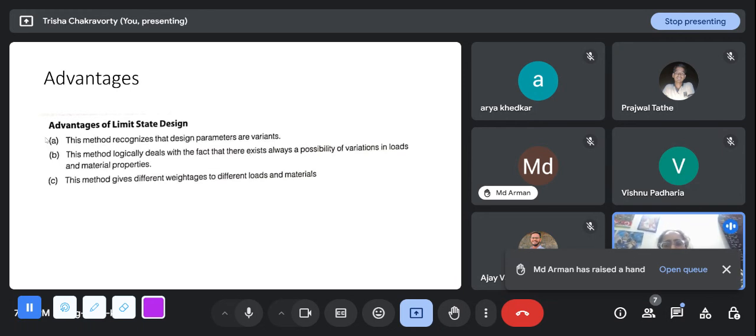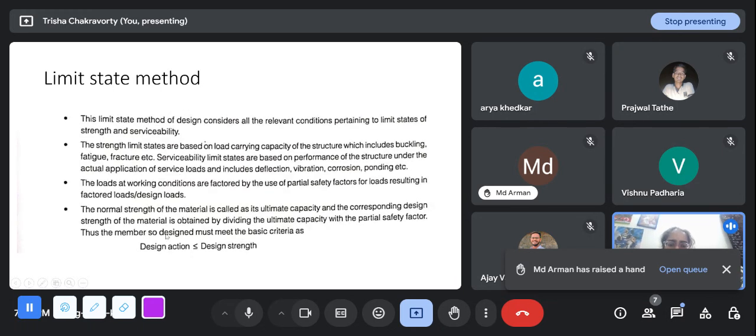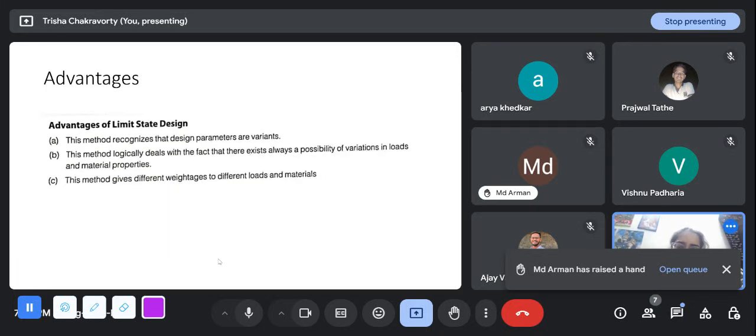So that is why we apply the safety factor on the strength. Suppose on 250 we are applying a safety factor of 1.1, that is, we are dividing by it. So 250 divided by 1.1 is something like 235 maybe, and that is what we are going to consider for the design. You realize that that makes the design safer, because we are assuming that the structure is weaker than it actually is.